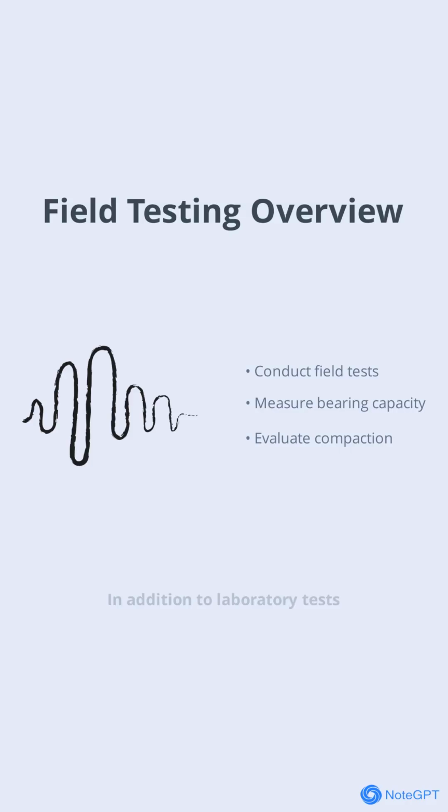In addition to laboratory tests, field testing is conducted to assess the performance of the fill in real-world conditions. This includes plate load tests to measure bearing capacity and test embankments to evaluate compaction and stability. Field testing provides immediate feedback and allows for adjustments to be made during construction.